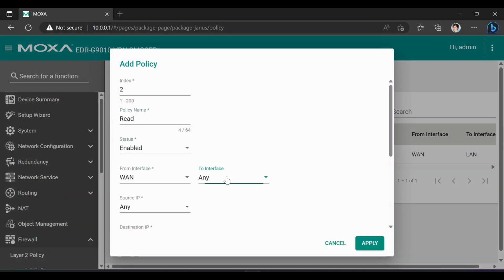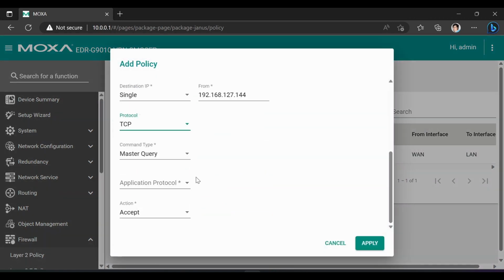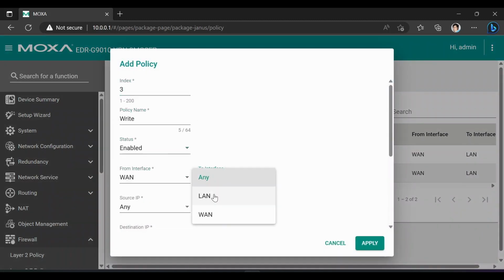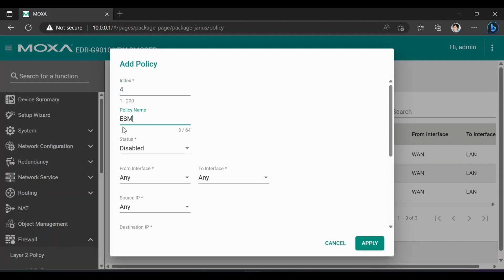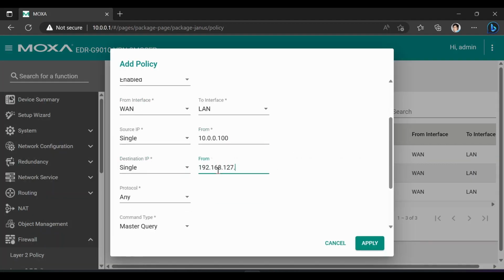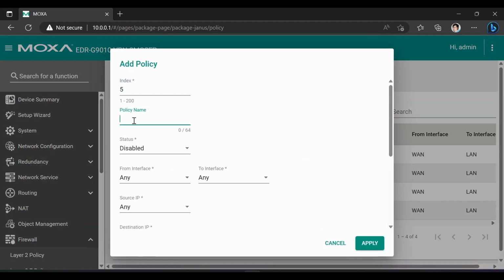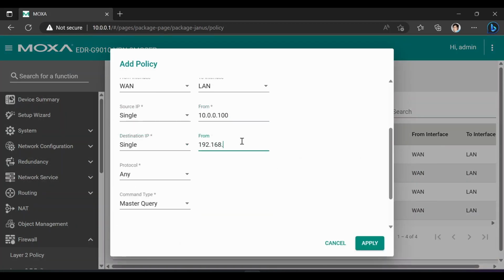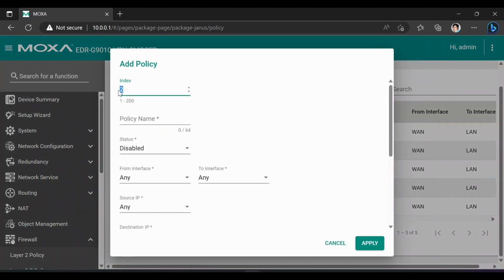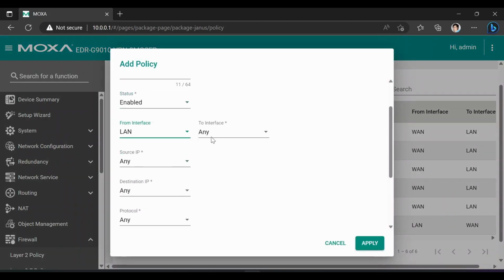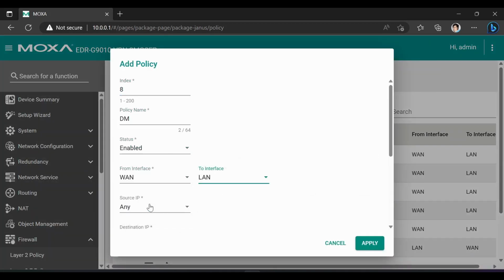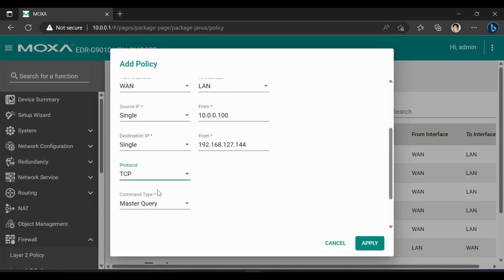In a similar way, I need to go through all DNP3 interactions that we want to allow and create a policy for each request and response that are expected. And since we have a default action of reset, the policies are going to accept the traffic and thus become a whitelist of communication patterns we want to see in our network. This is a time-consuming process, but it provides a better cybersecurity posture compared to the opposite approach, when we allow everything by default and deny only selected functions.